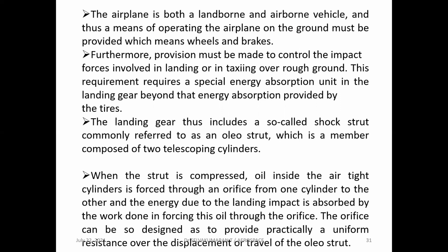The landing gear thus includes a so-called shock strut, commonly referred to as an oleo strut, which is a member composed of two telescoping cylinders. When the strut is compressed, oil inside the airtight cylinders is forced through an orifice from one cylinder to the other, and the energy due to the landing impact is absorbed by the work done in forcing this oil through the orifice.